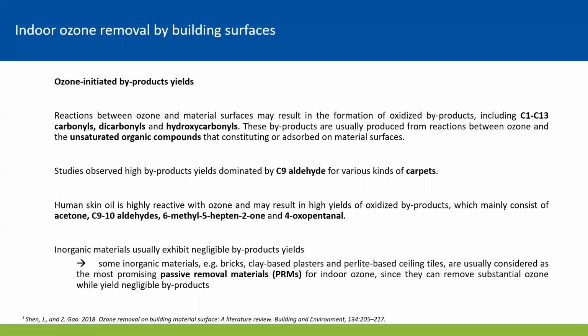The reaction between ozone and the materials may result in the formation of oxidized byproducts, mainly due to the reaction between ozone and unsaturated organic compounds. Some studies did measurements for carpet and observed that high byproducts were dominated by C9 aldehyde. And also, human skin oil is highly reactive with ozone. But generally, inorganic materials usually have negligible byproduct formation.